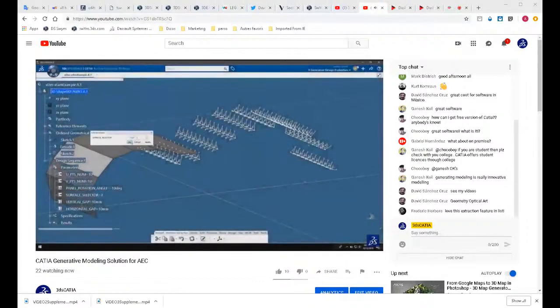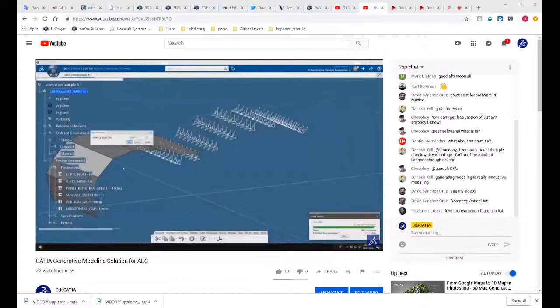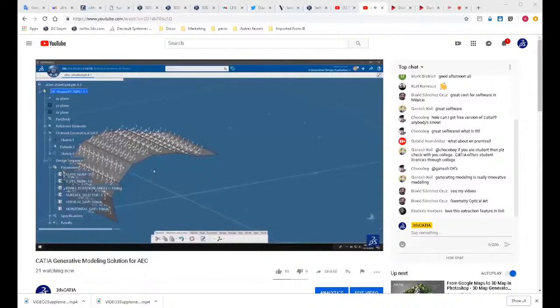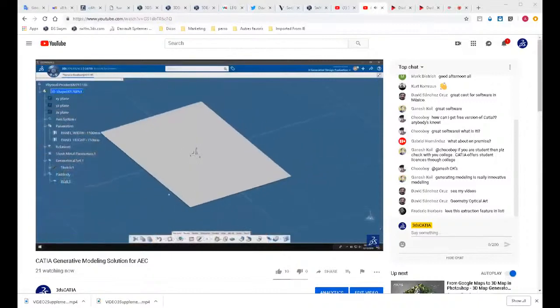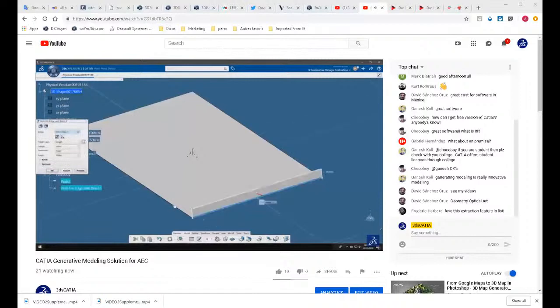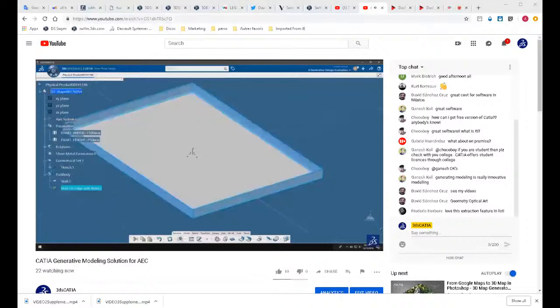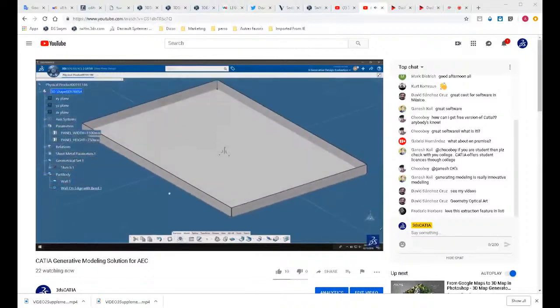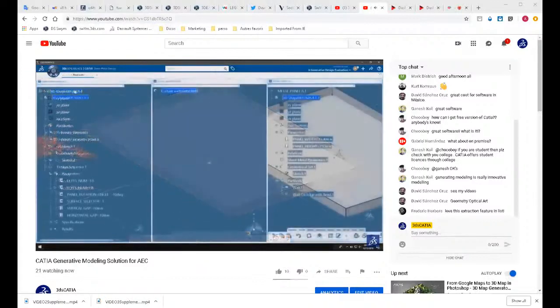I'm going to open this model in the Rich client, and you see that when I switch that surface selector, it still updates. And now I'm going to create a new part inside using the sheet metal design application. The sheet metal design application will allow me to make this panel, and it does the calculations for K factor for folding and everything like that. It does the notching based on the machining requirements. It includes an unfold view that I can project into a drawing for manufacturing.